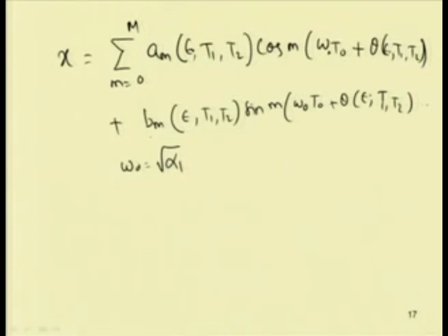So, we have not considered that thing to be a parameter of epsilon, but in this intrinsic multiple scale harmonic balance method, we are considering this AM and BM to be a parameter of epsilon and also a function of these different time scales T1, T2. If you are taking only two terms, we can take T1, T2, and if you take higher order terms, then we can take as many terms as we require.